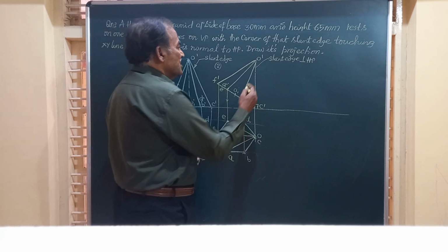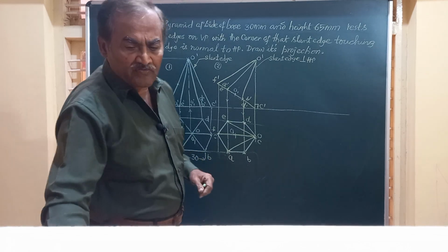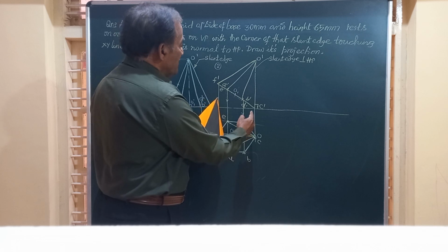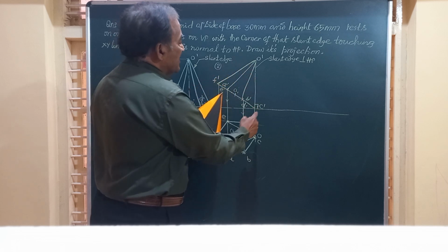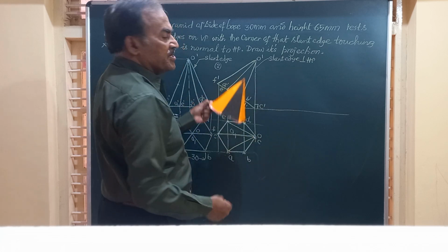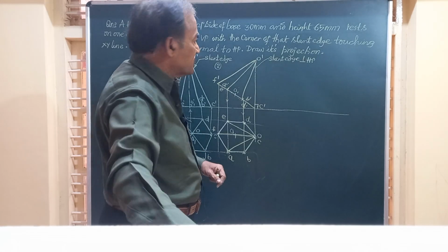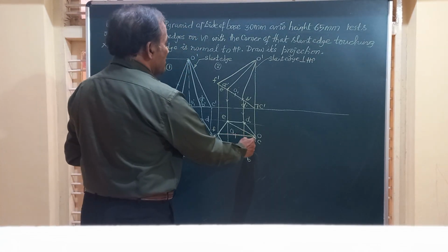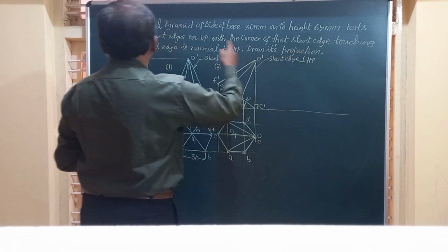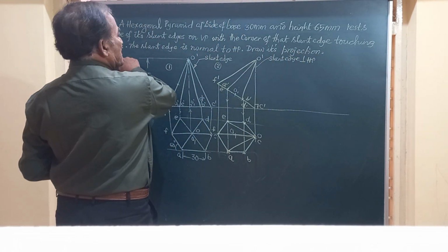Now friends, you can see here, the object is resting on C. C is one of the corners of the base, and that OC, the line connecting C to the vertex, is vertical. I have written here, that is perpendicular, means perpendicular to HP. And friends, what is required in the question is that this OC should be on the slanted touching XY line, okay, the corner.